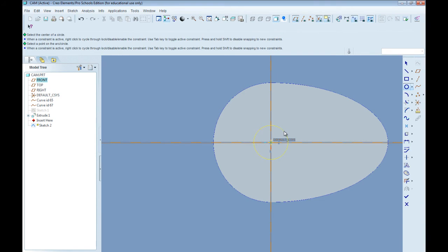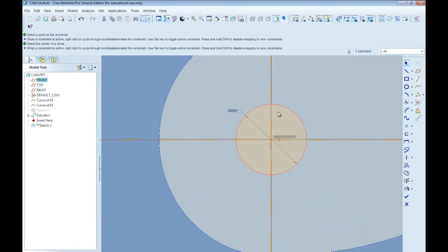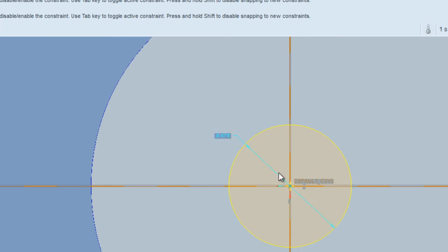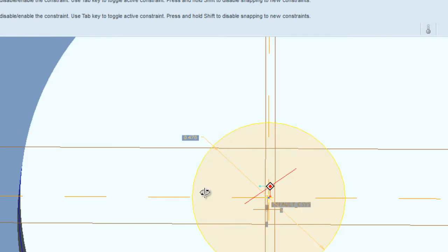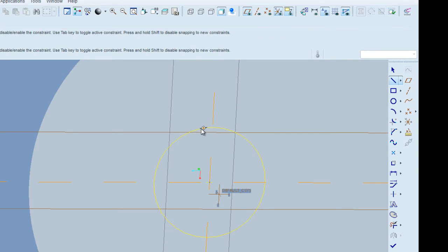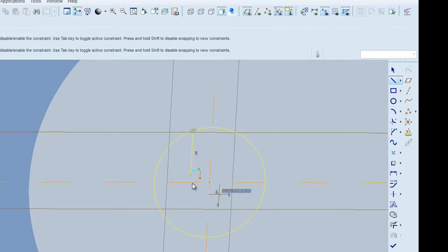So start out by drawing the profile of the axle. This is the same as the stud diameter, so say SDIA, enter. That's pretty much the size that we're looking for. But like I said, it's not just a circle, it's a cross. So we'll draw four lines in the center here. We have vertical lines and now we're creating horizontal lines.